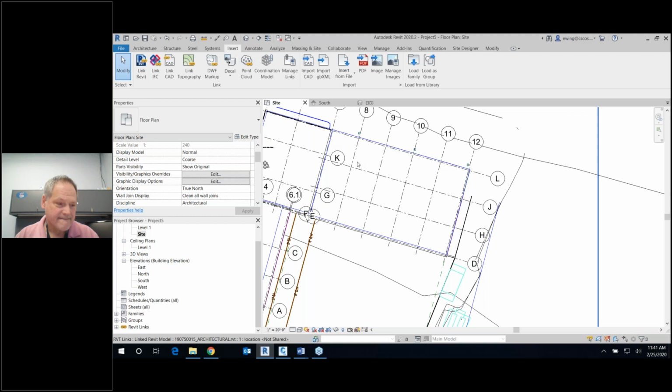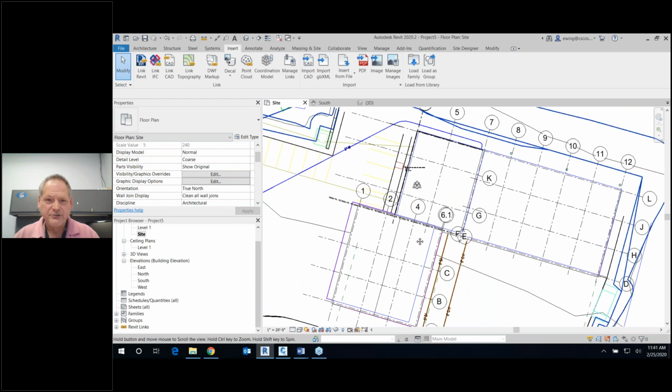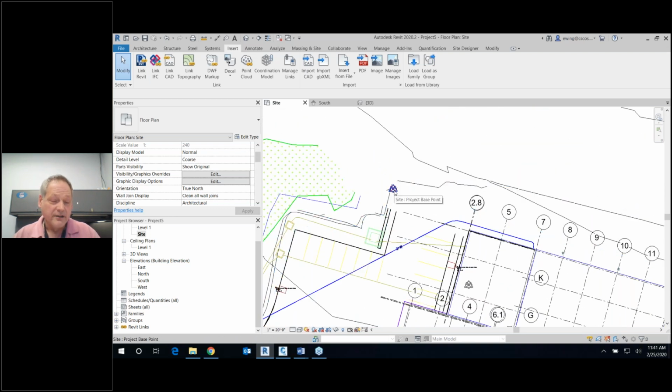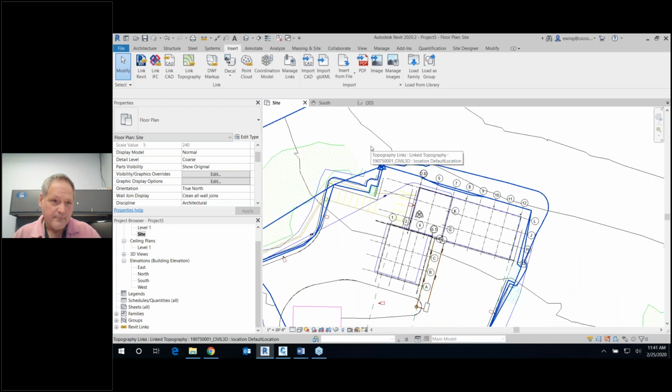Great. And Claire is asking the question, if we are working with Revit 2019, what are the major differences that we should understand while doing this process? The only real differences are with your project base point. You have to make sure that you have it unclipped. You're going to move the project. You're going to move your links. In terms of the BIM 360 functionality, you're going to have link topography, but it's a little harder. Sometimes it's off a bit.